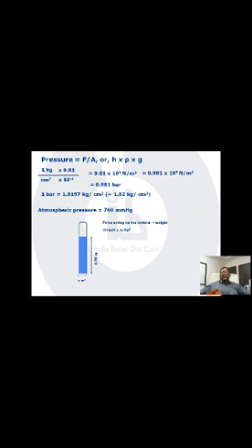In order to find out the mass, I need to find out the volume and the density. And the volume I know, the height is given as 0.76 meter and the cross-sectional area is A, so it's 0.76 A meter cube. And the density of mercury, we can assume, or we used to assume, in fact this is one thing you should put in the reference, as 13,600 kg per meter cube.